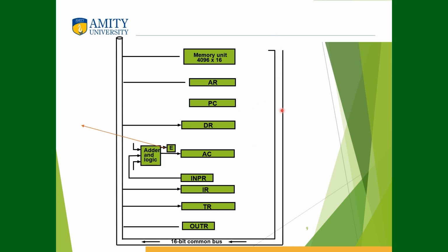Now this is the common bus that we will be using. Since the highest number of bits in our registers is 16, the common bus system will be used for 16 bits. Had it been any smaller, there would be loss of data, because the most significant bits of the 16-bit registers would be lost. There will be the control inputs S0, S1 and S2 in the bus, which will help us decide which register will be selected to load onto the bus.